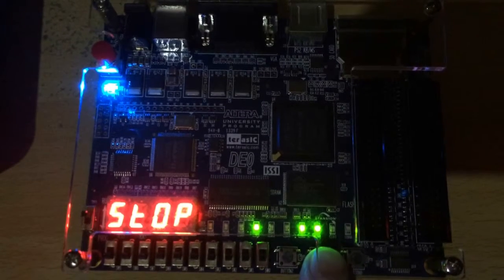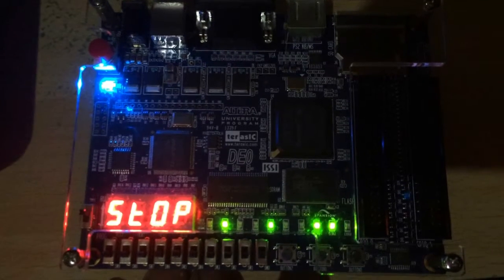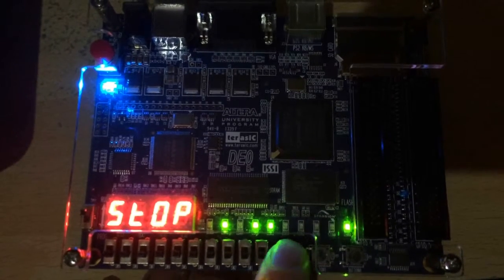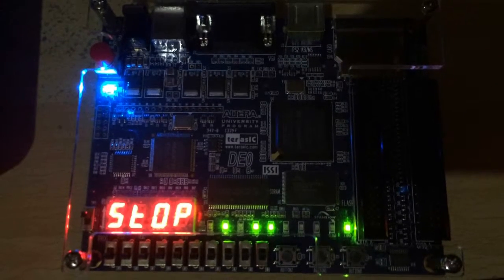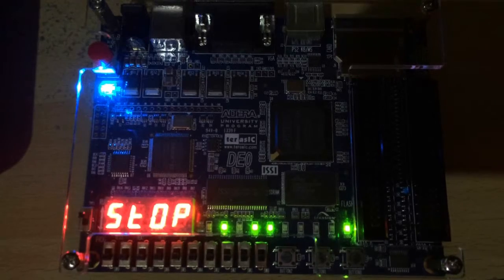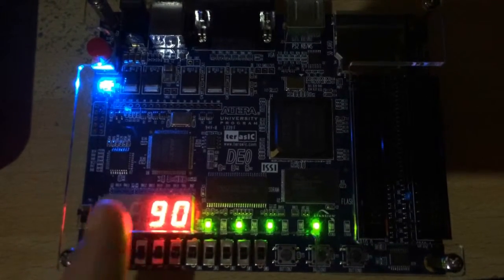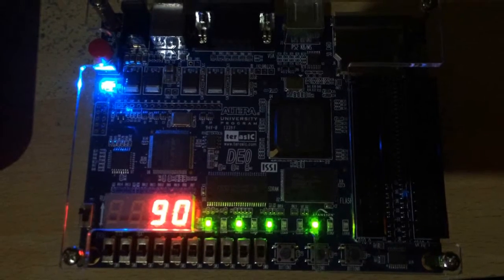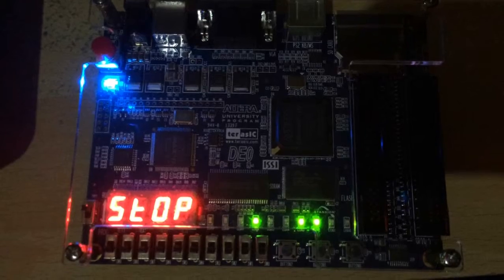and then I'll just hit it for the next bit again. I'll wait till we get to state F, press the pedestrian crossing button. After here it'll be tested for in intermediate state F1, where it'll then jump into state CRS here. We're told it's safe to go, have 5 seconds to get across, and then back to state A again. So that's basically it.